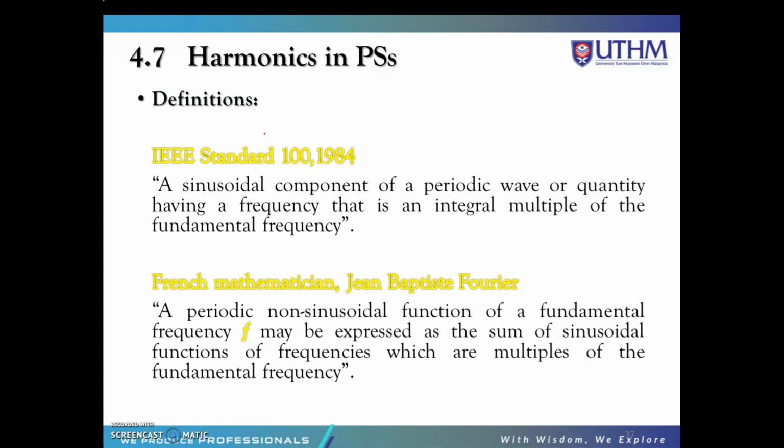And then from the French mathematician Jean-Baptiste Fourier, a periodic non-sinusoidal function of a fundamental frequency f may be expressed as the sum of sinusoidal functions of frequencies which are multiples of the fundamental frequency.